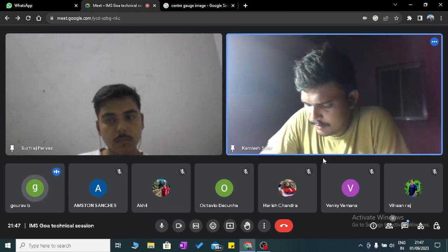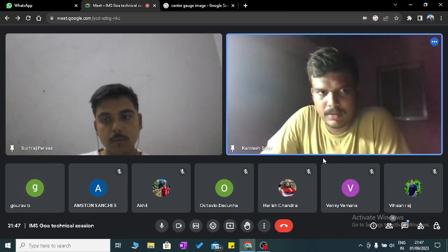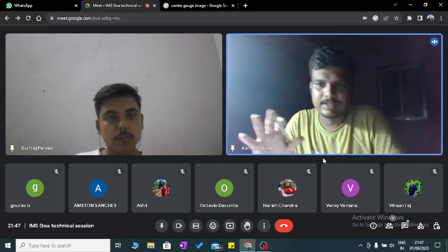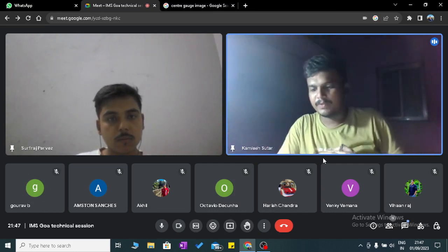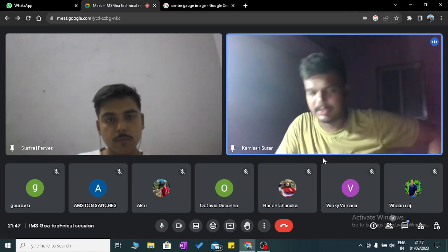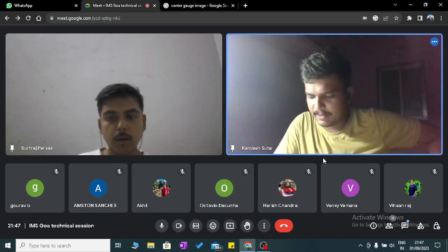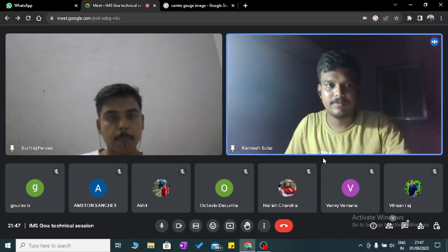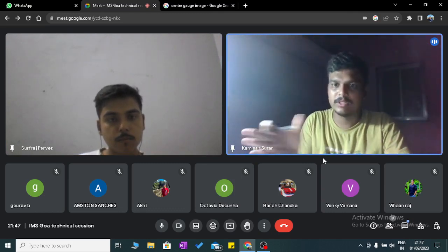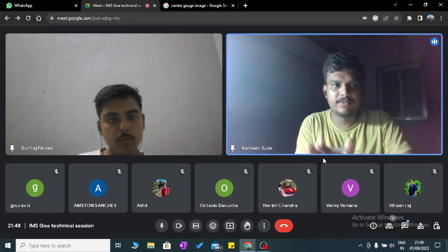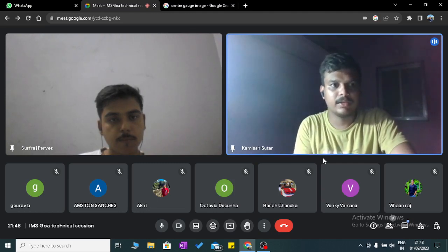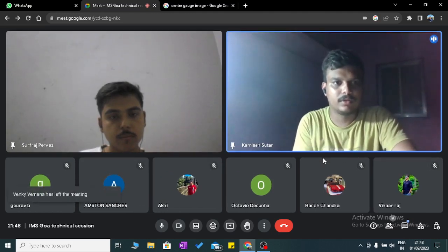And about thread cutting, I cannot explain it properly because I haven't prepared a proper answer for thread cutting, but I'll share it afterwards. All right. Okay. Anybody? Okay. Then the facing operation is there. Yeah, I forgot. Facing is when you just level the surface. You move your tool towards the center of your job and make a clean cut on the end of your job.